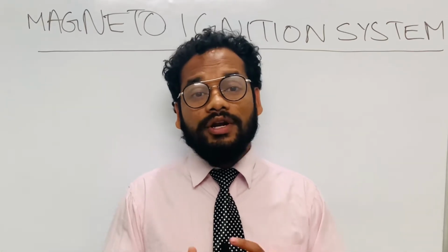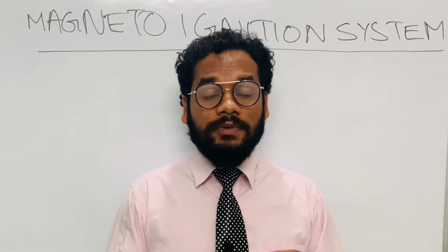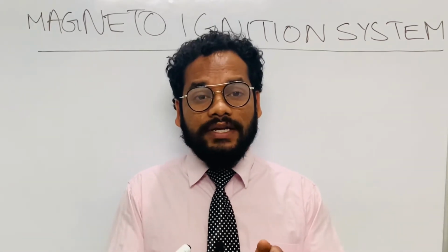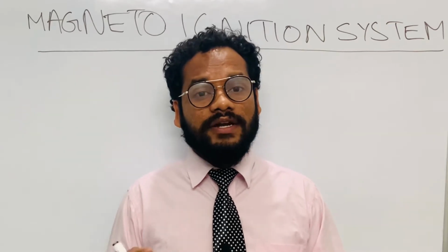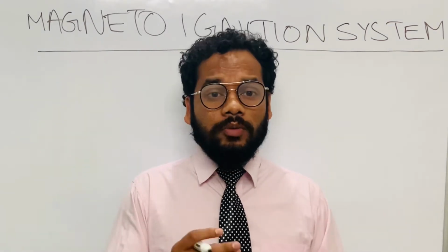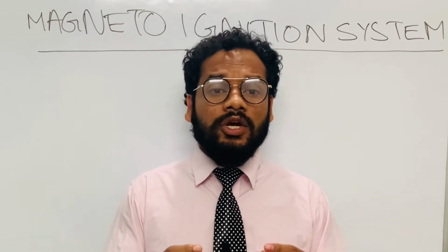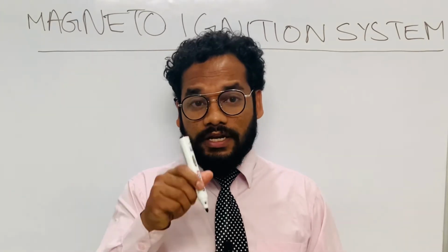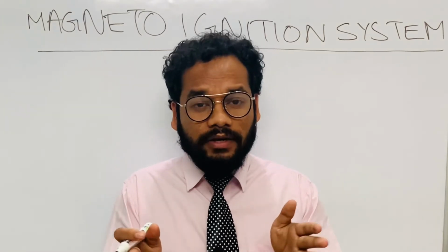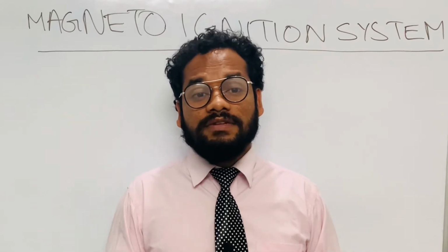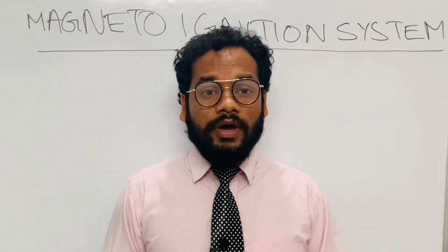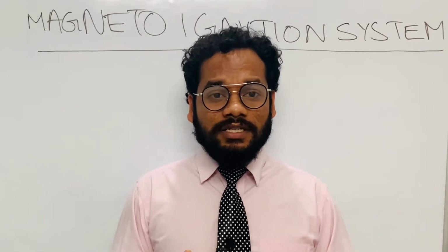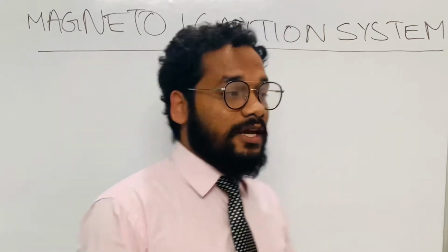The requisite alternating fluxes and voltages can also be produced by rotating the magnet between the poles of fixed transformer windings, and such a magneto system is classified as rotating magnet. A third technique is rotating soft iron inductor bars between a fixed permanent magnet and transformer windings. Such a magneto system is classified as polar inductor type. So we have discussed what a magneto is and its working principle. Now let us discuss how a magneto works using a schematic diagram.